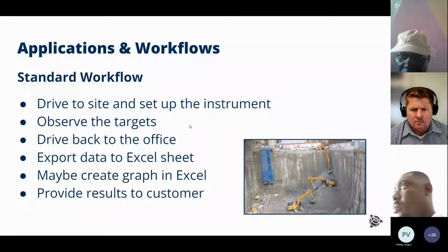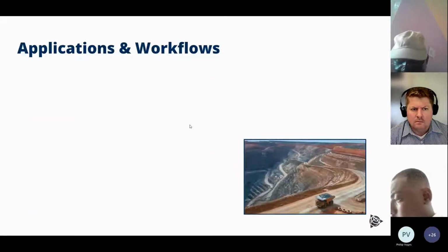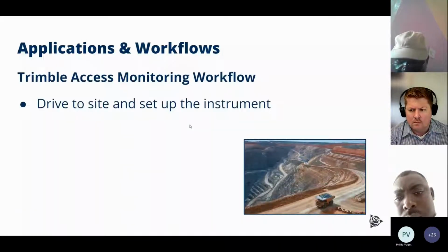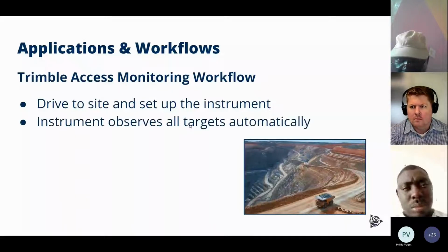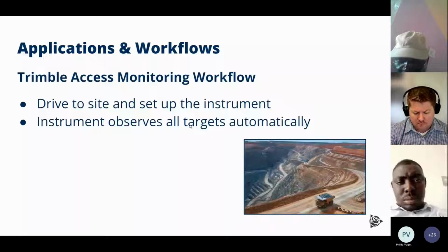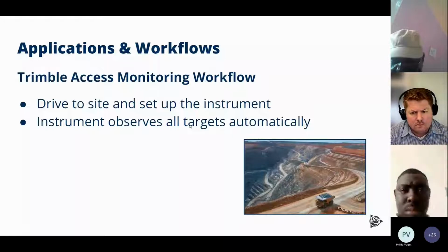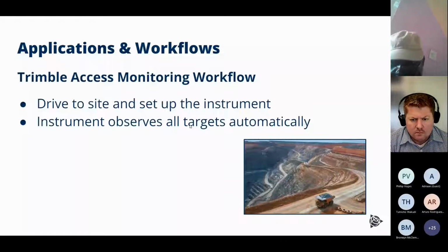If we now have a look how we can improve this by using, for example, Trimble Access and the Trimble Access monitoring app, still, of course, you would need to drive to site and set up the instrument. The second step is already much easier, because Trimble Access has all the functionality to allow the instrument to observe all targets automatically. You simply set it up, and then you activate the functionality, and then the instrument will observe all targets according to the schedule you want.